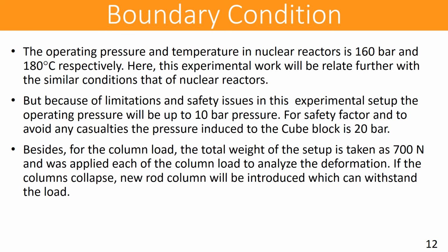This one is very important, the boundary conditions. As we know, the operating pressure and temperature in nuclear reactors are about 160 bar and 180 degrees C, respectively, but there are some limitations and safety issues, so we cannot go to that much higher pressure in our lab facilities.